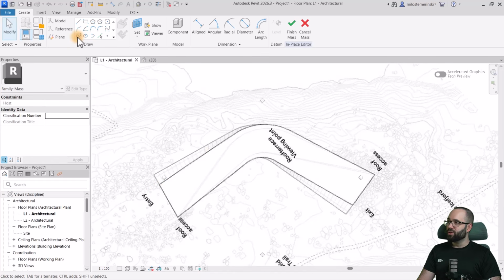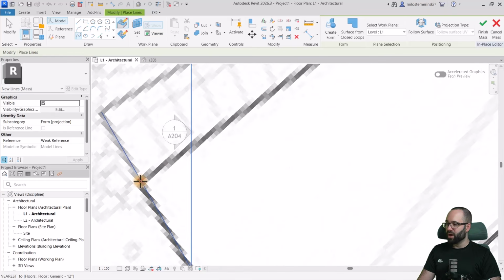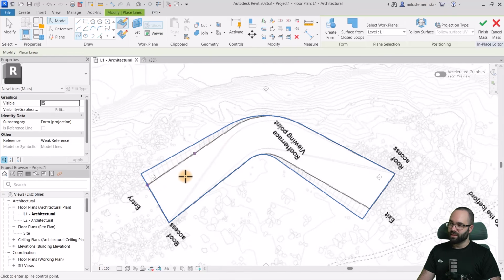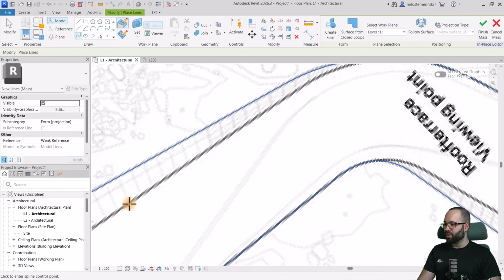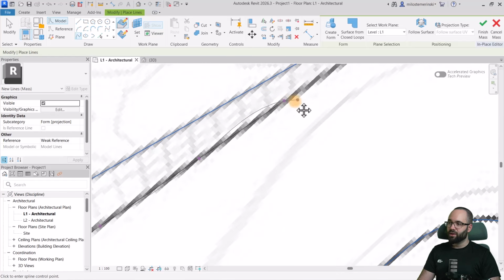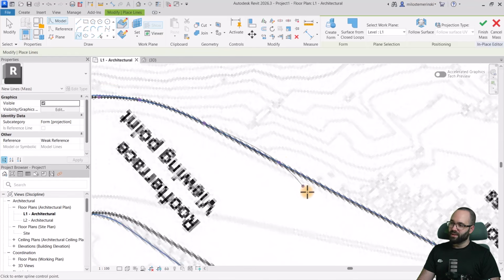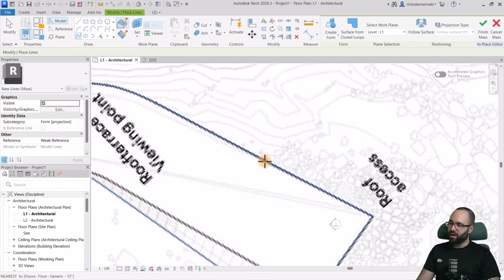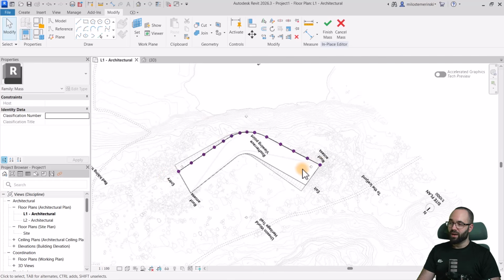So for that, I'm going to use the Spline Through Points tool. And then I'm going to start off from here. So the roof is this kind of white portion. So let's then create some points, and I'm just going to be placing points along the line here, and then here we start kind of following that curvature, perhaps a few more points, and then here we're just kind of placing it on the edge of our floor. Finish here, hit the Escape key a couple of times, and we have one of the splines.